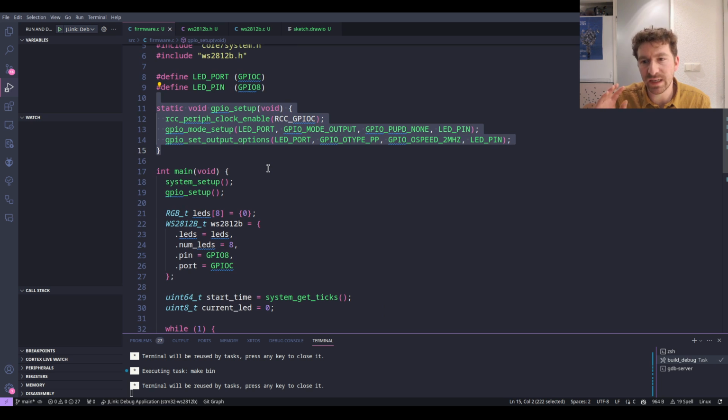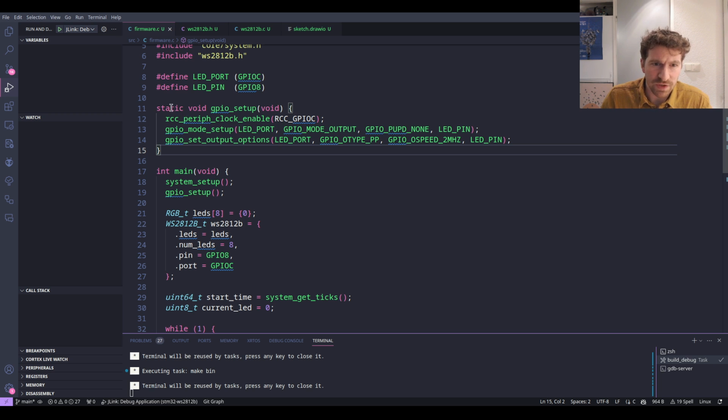It's totally acceptable that we configure the GPIO without having to do that as part of the WS2812 driver, because that's what we need to do for anything else, right? If we need to have PWM on a particular pin, we configure the PWM without talking about the actual GPIO we connect it to. And I think we should think about the same kind of thing here, like that should be more on the configuration side at this point.